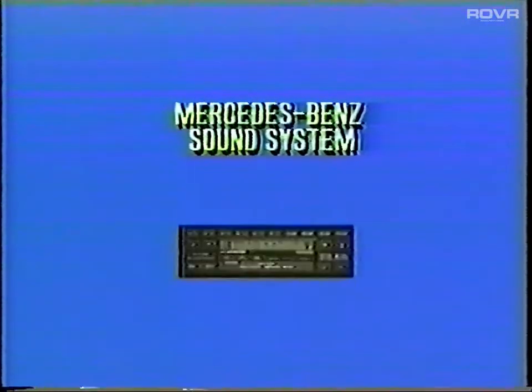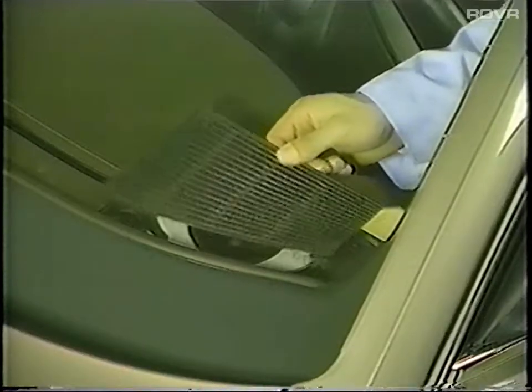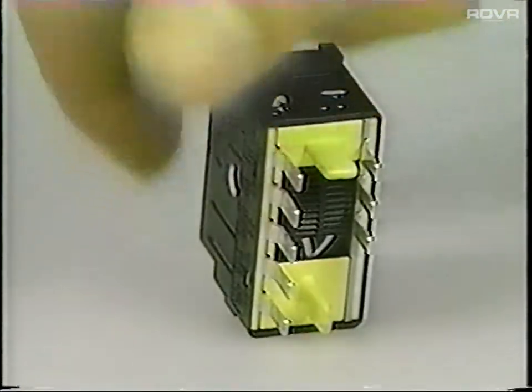The Mercedes-Benz sound system consists of the following: the Becker Grand Prix Electronic 780 with amplifier coupling, left and right amplifiers, which are dual amplifiers located under the rear seat back. The left amplifier serves the left side speakers, and the other serves the right. Each side provides a power output of 50 watts per channel, for a total output of 100 watts RMS. The speakers are located in the dashboard, hatch shelf, and front doors, and there is a new high-impedance fader switch identified by a white dot and a yellow base.